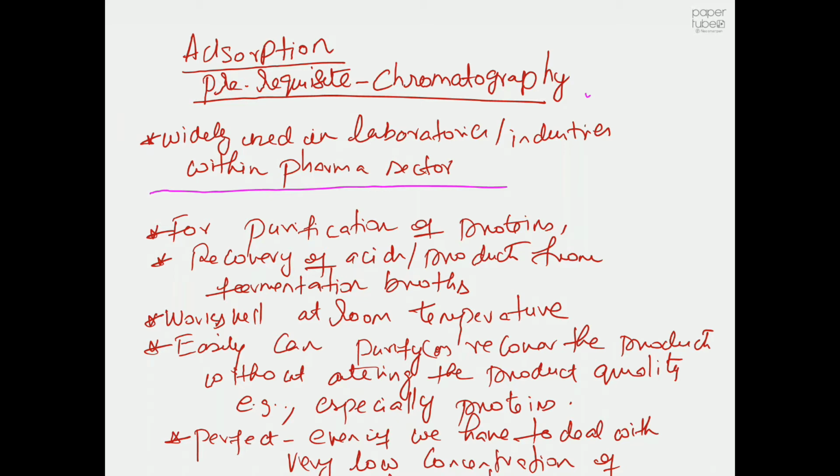In pharmaceutical industries, it's widely used mostly to purify proteins or some fermentation products. If you want to remove some particular product from the fermentation broth, and if they are specific to some adsorbent materials which we are going to study now, then we can go for this technique.